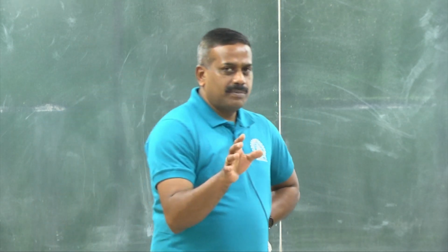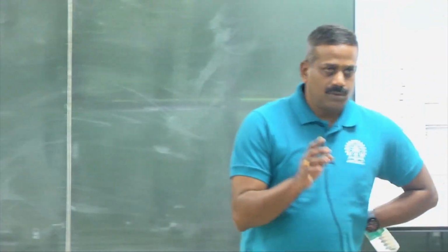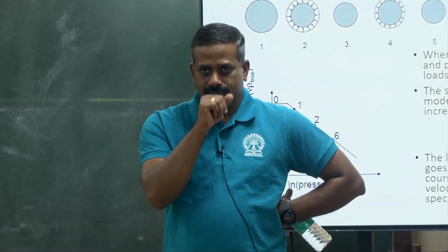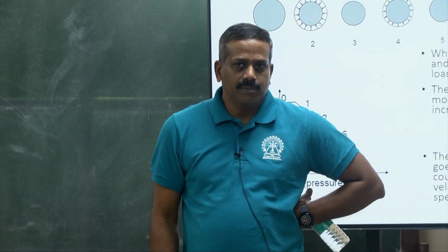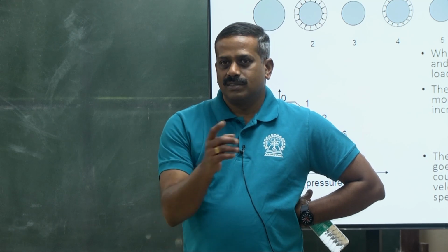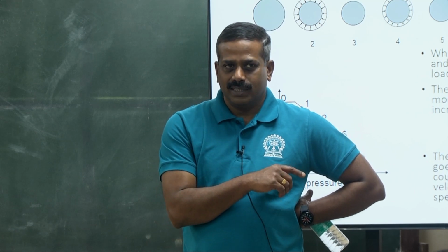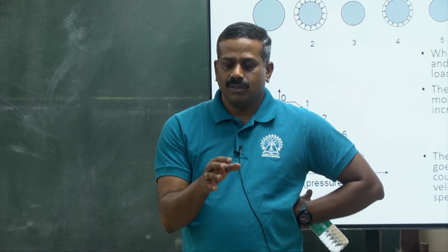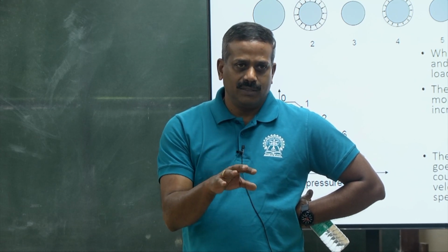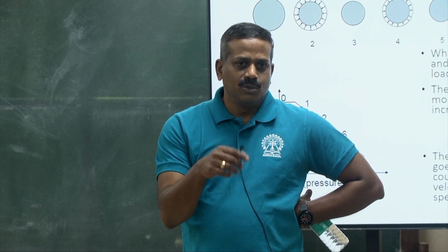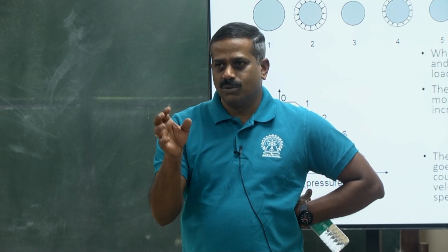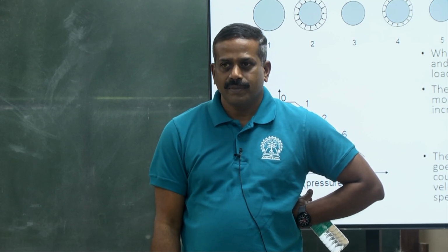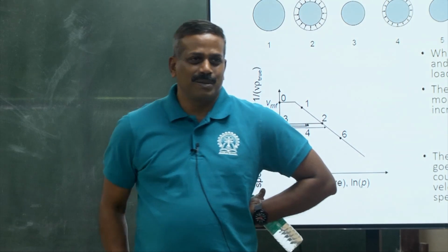One common application of why we care about void fraction is agglomeration. When you are agglomerating any type of powder, same thing we talked about, binder load, right? Yesterday, how much binder you want to add. This void fraction will influence the load of binder that you want to add during the agglomeration process, so that you get good granules. Okay, we'll come back to your question.